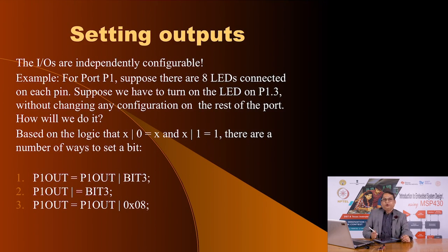Since the input output pins are independently configurable, it is very important that we understand what information we are writing into any direction register, then outputting into the output register, reading from the input register, and selecting appropriate pull-up values by enabling or disabling the REN register, and so on.